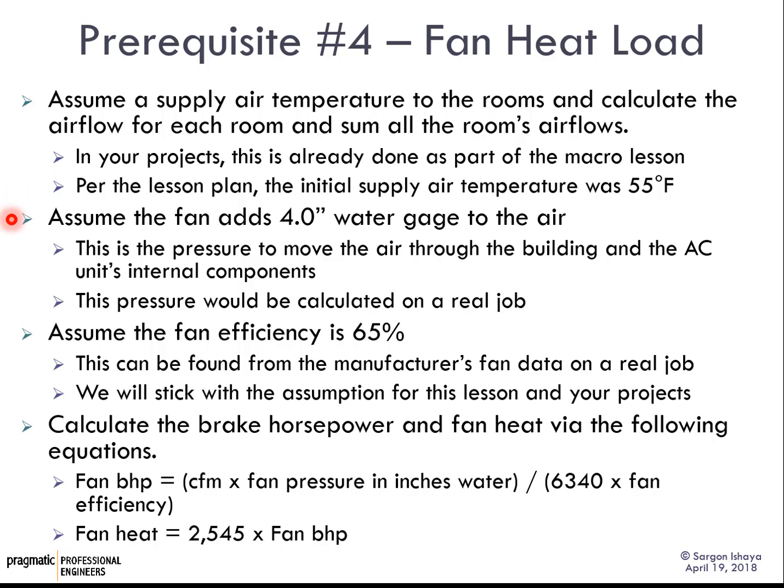We are going to assume that the fan adds 4 inches of pressure to the air. Okay? Now, this is not the external static pressure. This is actually the amount of fan heat that's added is based on the total pressure, internal and external, that the air conditioning unit's fan has to overcome. We are going to lock that value in at 4 inches.